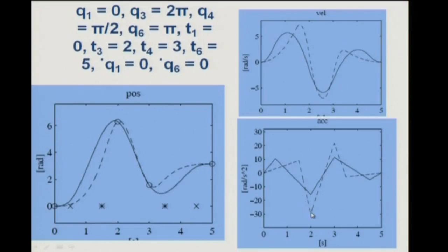Now, if you compare the accelerations, this dotted one has higher accelerations. Okay. So, it is a less preferred one, because to get higher acceleration you need larger motor torques for this problem, which is not desirable. So, your motor torques are not determined only by your final payload, but also by how quickly you want to move things, and what interpolation you use. So, everything demands motor torque, so it will add to it.